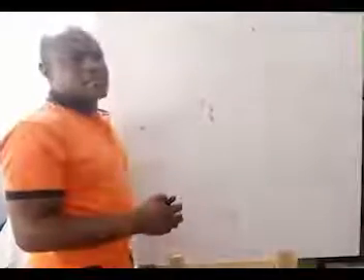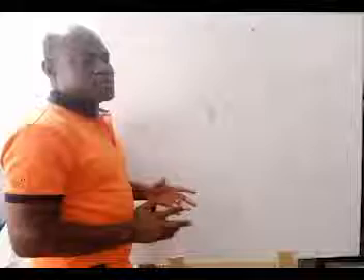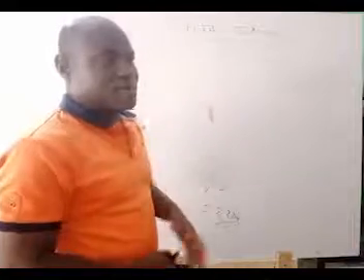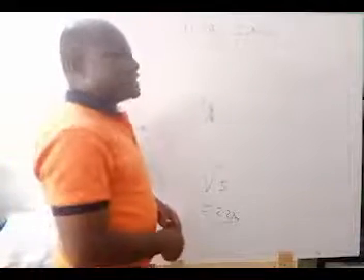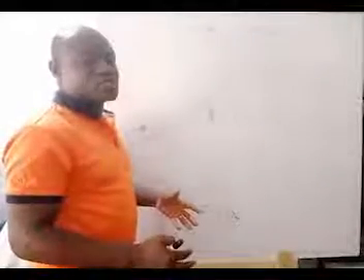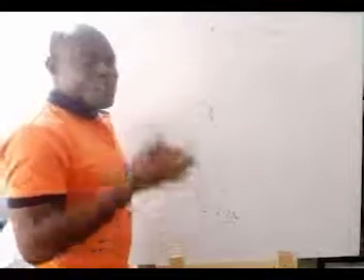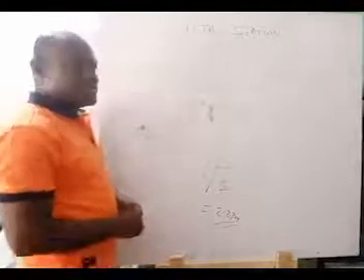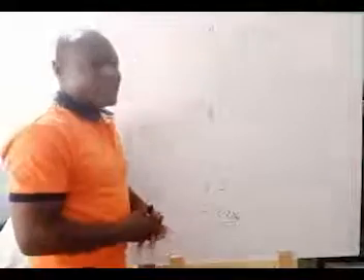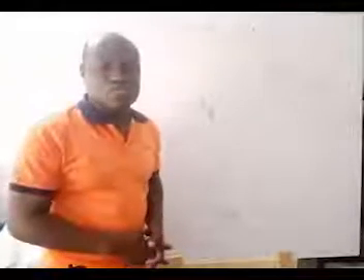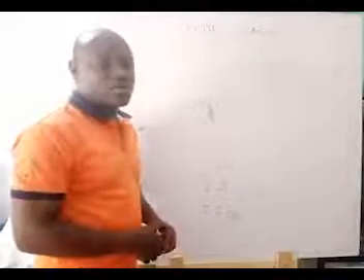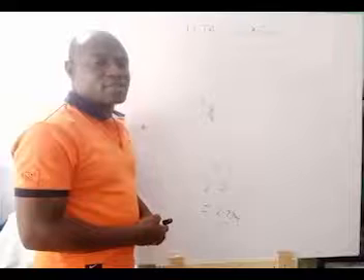One other thing that the total station will need to orient itself, we've talked about giving it its position coordinates and then the direction, the bearing. But there might be cases on site where you may not have a coordinate, or a point to set the instrument on. Maybe the points are on a wall or something. Site conditions might force you. I've encountered that a lot of times where site conditions force you to put controls on the wall. So maybe you have three controls, three points of known coordinates on the wall, and you want to use them to orient the total station.